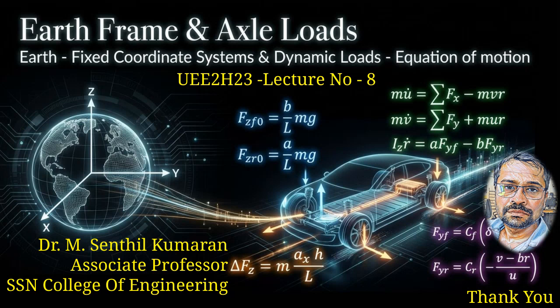This load transfer does not move mass, it redistributes tire grip. What the front axle loses, the rear axle gains, and vice versa. Finally, we connected load transfer to real engineering decisions. Axle loads directly limit traction, braking, ABS behavior, and motor torque usage. The key takeaway is simple. You cannot design power, brakes, or control systems without understanding axle load transfer, because physics, not software, sets the ultimate limits.